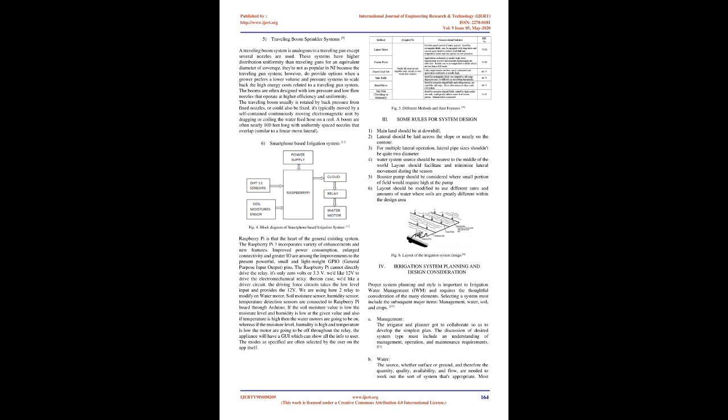Each sprinkler features a pressure regulator set at 10-20 psi. With proper management, application efficiencies with center pivot systems are often 75–90%, depending on wind speed and direction, sprinkler type, operating pressure, and tillage practices.